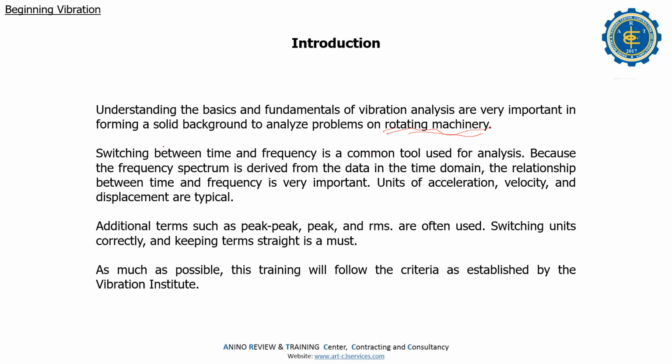Switching between time and frequency is a common tool used for analysis. The frequency spectrum is derived from the time domain. All vibration comes from the time waveform, and then the FFT, Fast Fourier Transform.